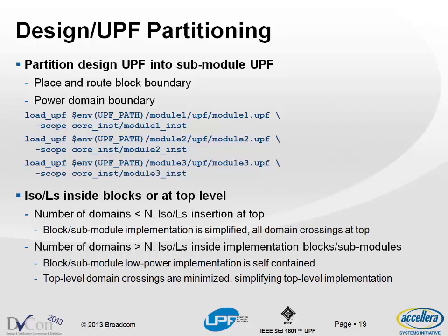But as you keep scaling your design, and if you have 20, 30, 40 power domains, if you're going to have all the power management cells sitting at top level, from an implementation standpoint, it becomes a little more complex to manage routing, managing, and connecting these power management cells. So it becomes better if you move them inside the block. The block itself becomes self-contained. You can verify the block standalone. It's complete with respect to power management. So it's a trade-off that you have to make depending on the size and complexity of your design.